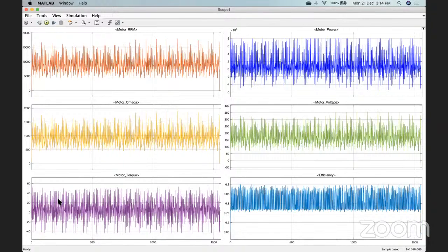And based on that you can select your motor, and you can also select your voltage ranges. So if you look over here, the motor is expecting somewhere around 300 or 320 volts, or sometimes 350 volts as the peak. Okay, whenever we are touching 18,000 RPM, it is touching 350 volts.